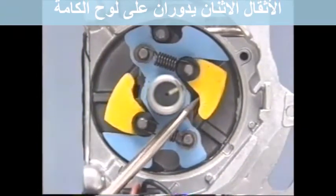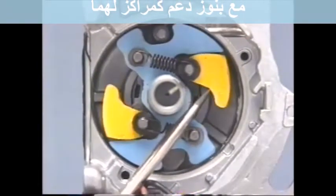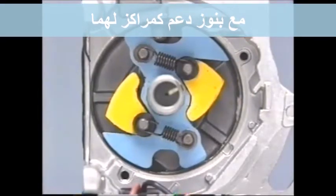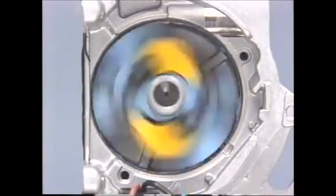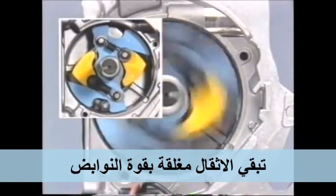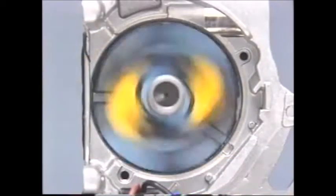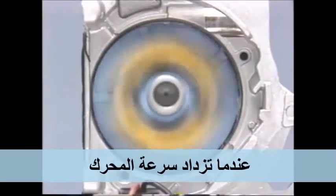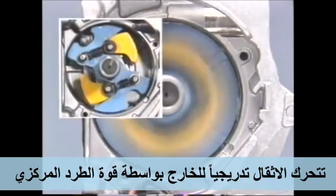Two flyweights rotate on the cam plate with support pins as their centers. At low engine speeds, the flyweights are kept closed by the force of the springs. As the engine speed increases, the flyweights are gradually thrown outward by centrifugal force.